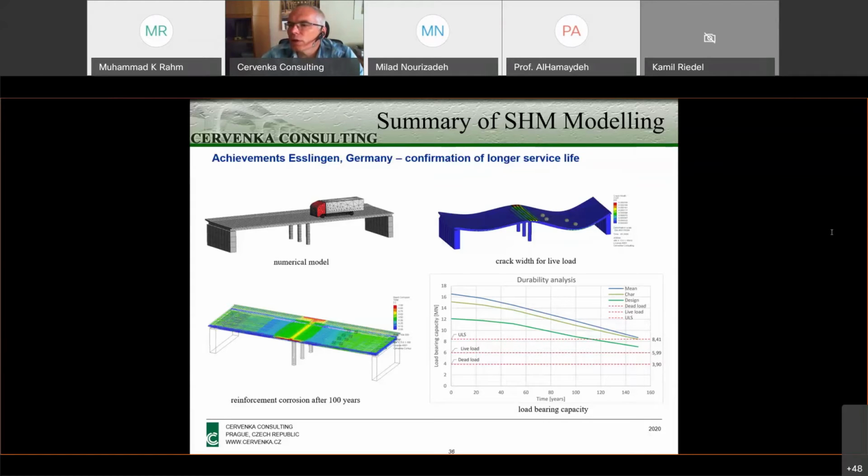Okay, there's another question. Is uniform corrosion assumed, or do you use assumptions for the pit distribution? Yes, of course, I will come to that later. When you apply this surface condition or this chloride concentration condition, you can select. This is one of the parameters that you have to define as a user, whether you can expect uniform corrosion or pitting corrosion. In this case, because we expect that this chloride concentration will start at certain locations, we assumed pitting corrosion.